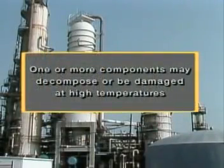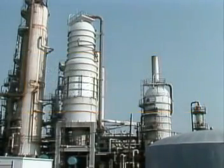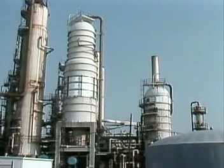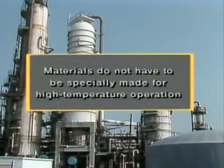First, one or more components in some liquid mixtures may decompose or be damaged at high temperatures. If such a mixture is distilled at high temperatures, an unwanted product may result. A second reason for using vacuum distillation is that running a tower at high temperatures requires more energy or fuel. Operating a tower at lower pressures allows the distillation process to be accomplished at lower temperatures, which requires less energy. A third reason for using vacuum distillation is that a tower that's designed to operate under vacuum, and therefore at a lower temperature, can be constructed of materials that do not have to be specially made for high temperature operation.